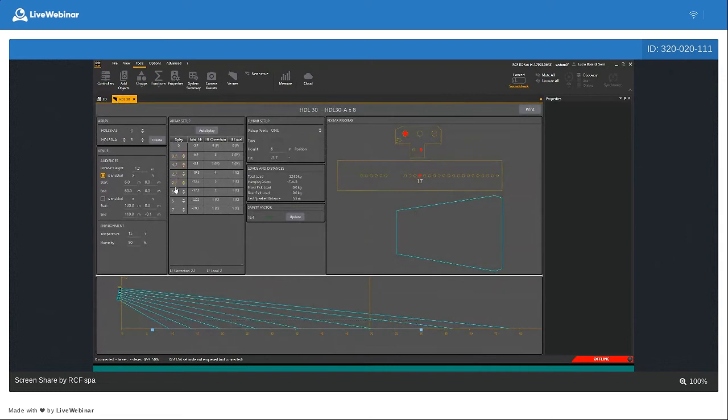So, coming back to our venue, you can see the angles that we have here, and the number of modules, 8, and the height of the flybar. We have all the data we need. We have to copy this data in EaseFocus to create the same cluster, okay? So let me open EaseFocus to show you how to simulate this venue with this system.